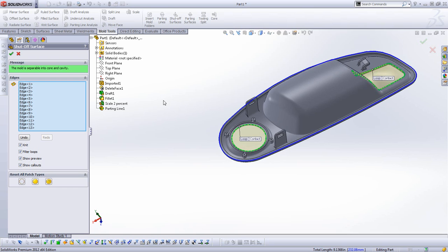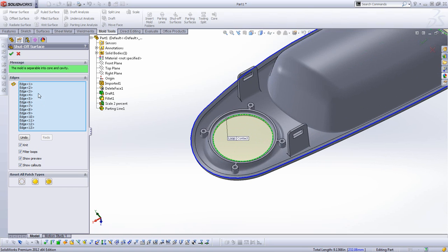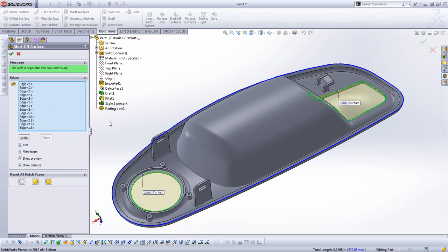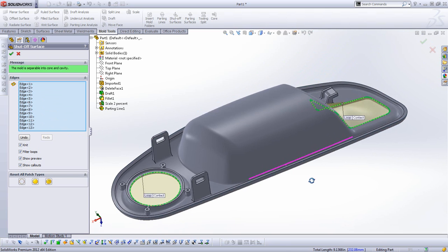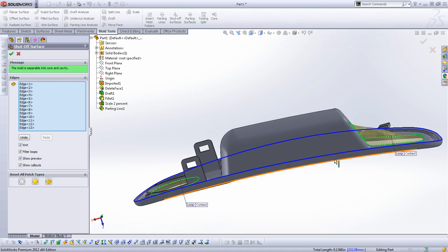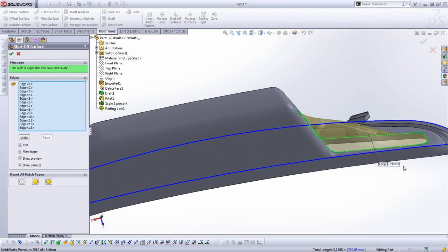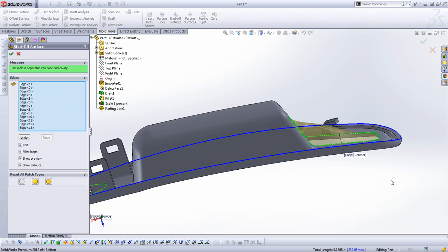And then if you look at this, you've got these little leaders. It found all the shutoffs that it needs to create on those two items all by itself. But if I rotate this around, you can see this one bows out, which isn't really a good machinable shape. It may be functional if you could machine something that would shut off that well, but that's probably not going to be reality.